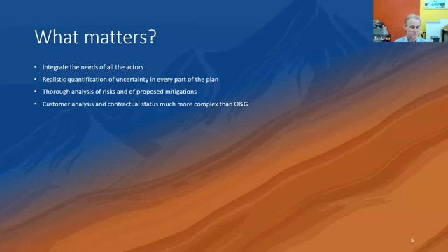So if you look at the subsurface, for example, what is a realistic understanding of the heat in place, a realistic understanding of the productivity of the wells, not immediately, but also in the medium term, and of the flow of heat to those wells, and that's just the subsurface. And then you've got to look at the uncertainty in the equipment you put in there surviving for the whole field life. For example, lots of the chemistry of various geothermal waters is very aggressive, and you might not see that aggressiveness to start with, depending on your sampling programs. But again, you need to be sure that if you need to remediate those wells, you're able to do so, and you've put that in your economics as well.